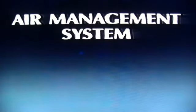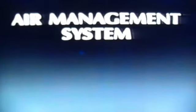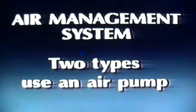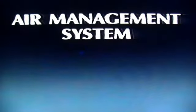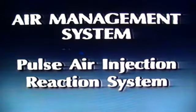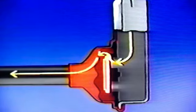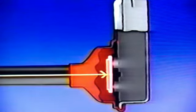The next output control we want to talk about is the air management system. There are 3 types of air management systems. 2 of them pump air with an air pump through the air management valves to the exhaust. The 3rd type, called the pulse air injection reaction system, is found mostly on smaller 4-cylinder vehicles and is located in the exhaust manifold. This system uses natural alternating vacuum pressure pulses to pull air into the exhaust through the check valve. When the vacuum pulse shuts down, the check valve closes so the exhaust doesn't get back into the